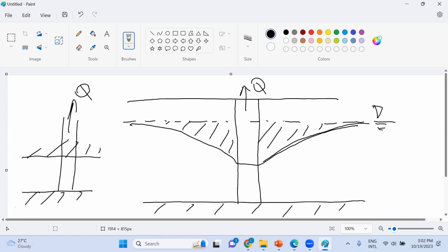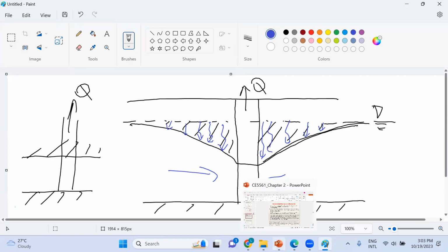For example, think about a wet towel. If you take it out from the basket, what will happen? Water starts draining down from this unsaturated layer. So this is now acting as a second source of water in addition to the water coming from the aquifer, from the saturated part. Water starts coming from the unsaturated part as well. So this is a second source of water to the pumping well, right? So that is the difference.